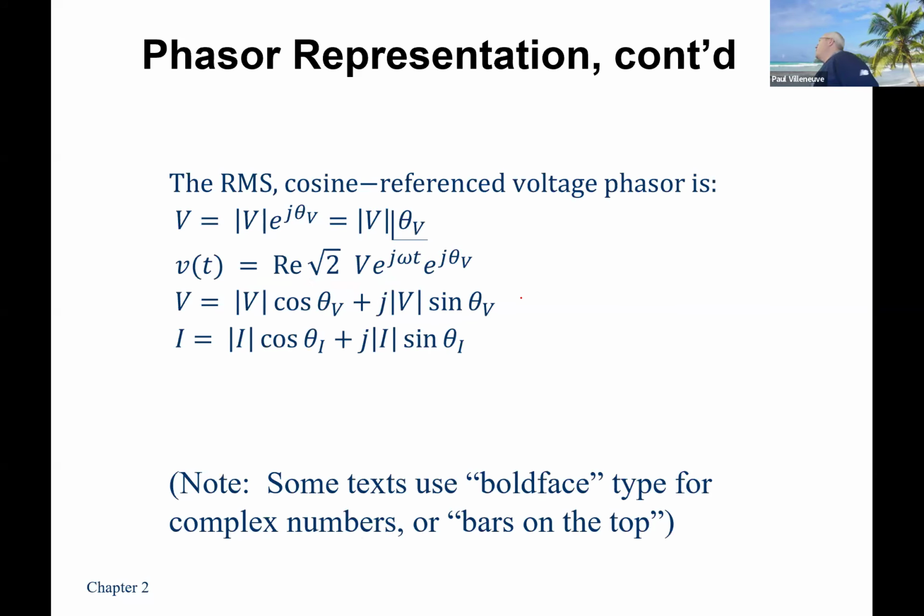All right, so we're going to use our Euler's identity. And again, engineers are efficient, or lazy, depending on your perspective. So it's much easier to write V at an angle of theta using the angle symbol, as opposed to writing it V e to the j theta. Mathematically, the first phasor representation is the correct way to write it. But the second way is just hopefully more obvious.